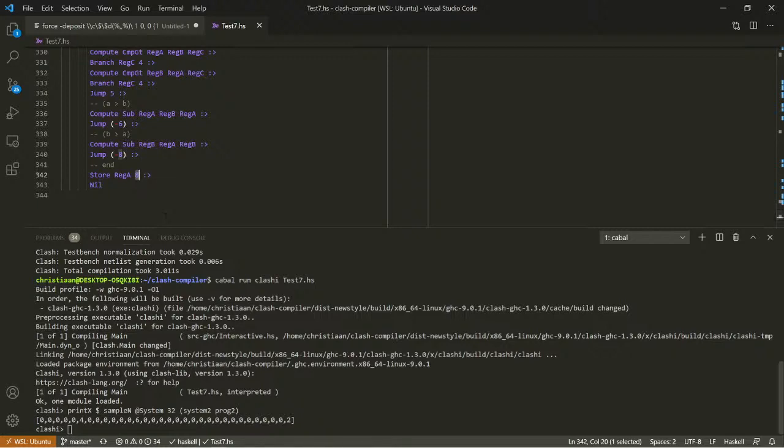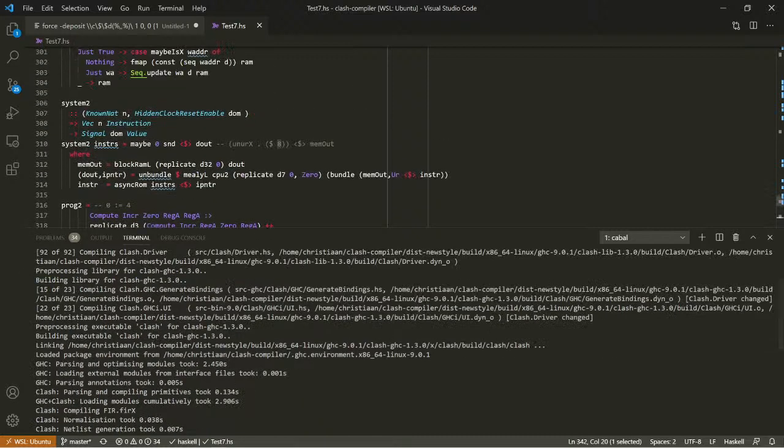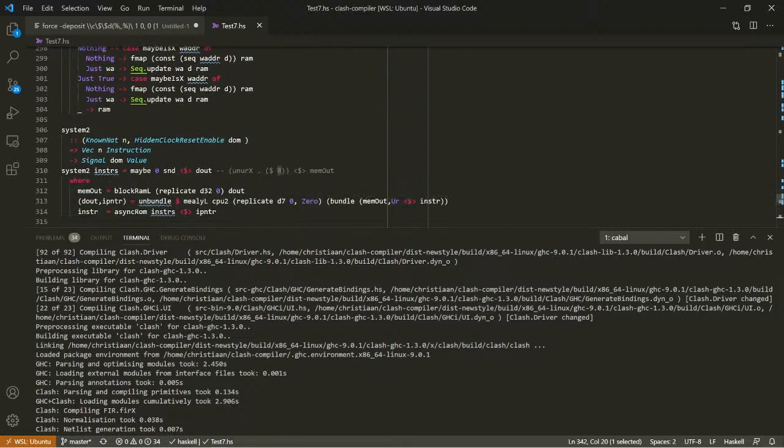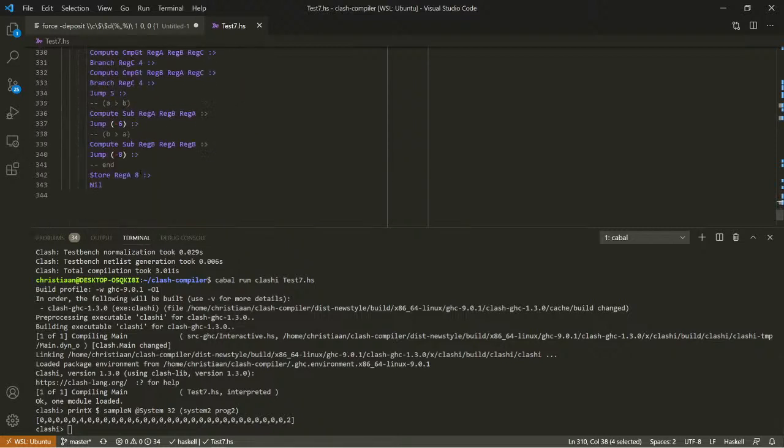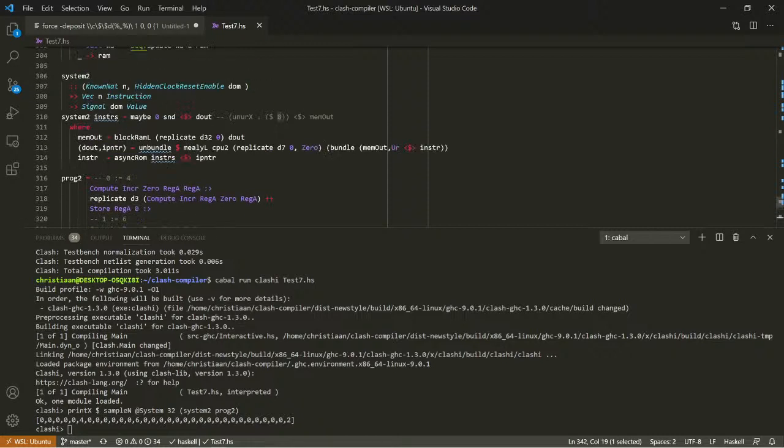So how do I currently print this output? Well, basically I monitor the write port that we're sending to the block RAM and just output the data that's being sent there. And so that's how I get this output. That's not how I started out though. I knew that it was going to be sent over to location 8.